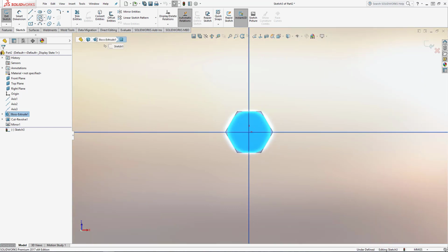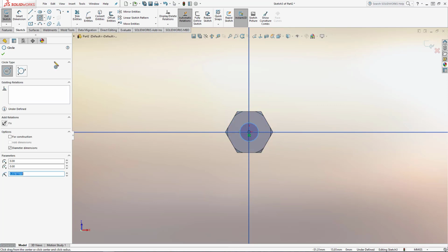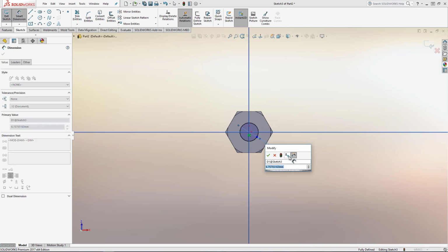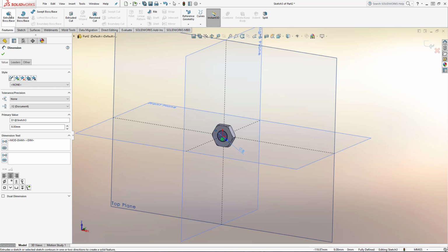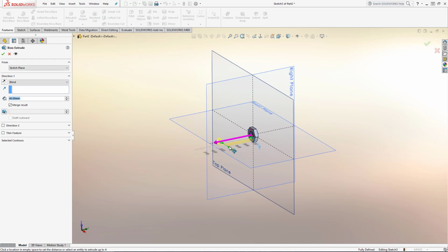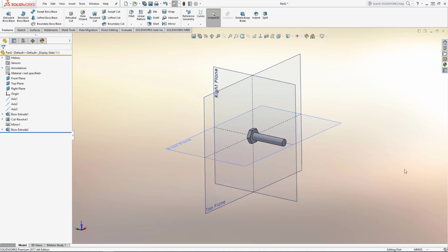So here we are, we're just going to put a circular sketch in here, we're going to lock it to the origin again, drag it out so visually it looks about right, put a dimension on there, and I think we'll make this an M8 bolt. So if you just enter 8, and then again we can shortcut to the extrude feature straight in there, and we'll just use the drag arrow and we'll lock this one at 40 mil. So you can see there 40 mil. I use the ruler just to snap to the nearest 10. So there you go, we've got the shaft of the bolt.